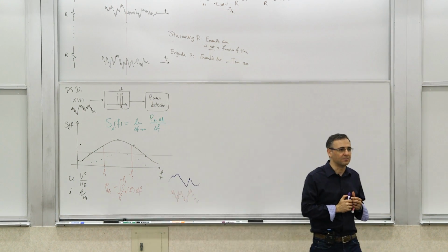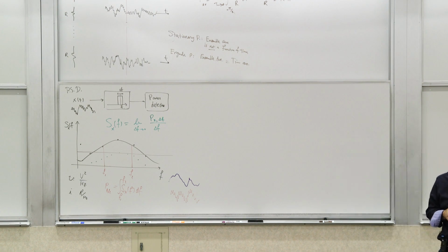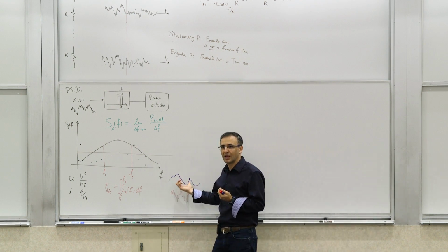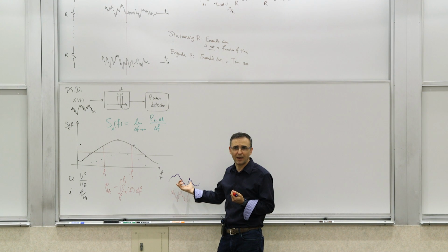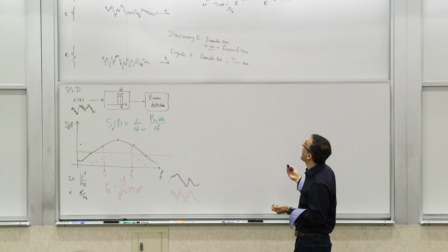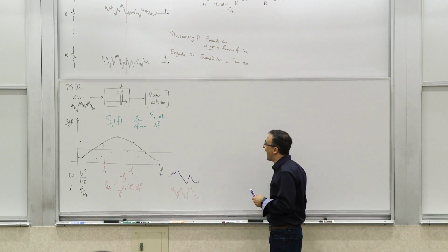They're both random, but you can see that they're different. From a frequency domain perspective, you can imagine that one of them will have more high frequency power content, and one of them will have more low frequency power content, right? Which was completely lost if you did some sort of regular averaging, like what we did with the average power.